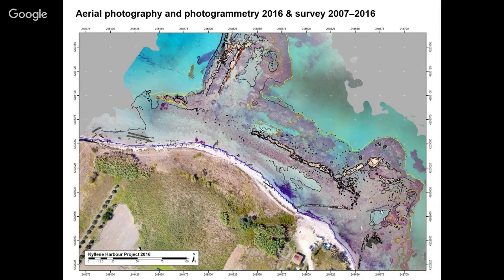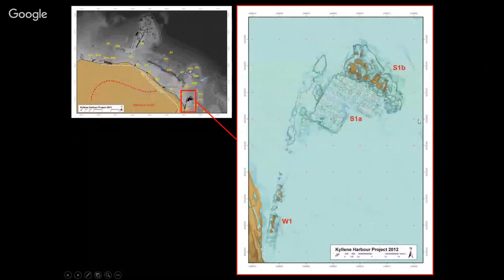So there, I didn't actually know that it would work, because you have a problem with the refraction, so that the sight lines, how they go from air to water, you always get a bending, and that means I had a guess that you could actually correct it by putting in loads of control points into the sea. So you actually add them to the model and measure those in with the total station with precision. And I'm just going to show the Greek tower.